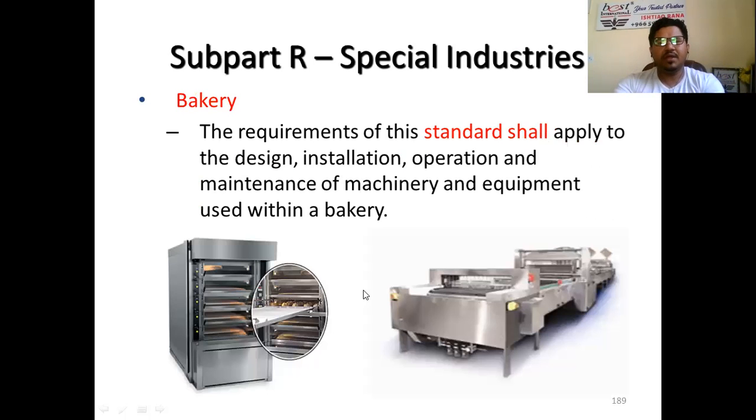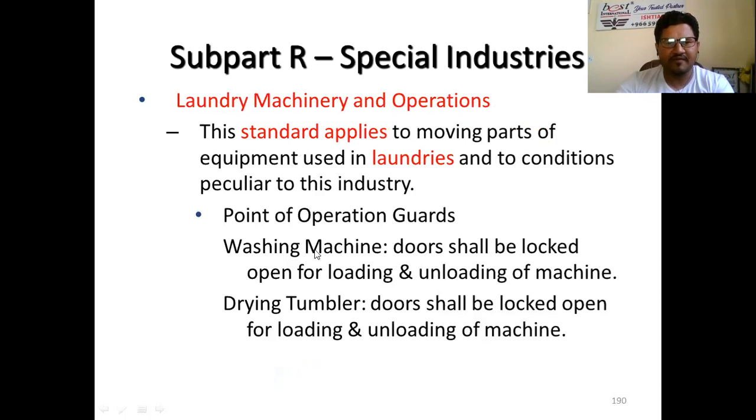Now, if you have a bakery, the requirements of this standard apply to the design, installation, operation, and maintenance of the machines and equipment used within a bakery. As I told you, as per the industry type, be more proactive, including laundry and operations. The same standard applies for laundries, and let me give you an example, like point of operation guards: washing machine doors shall be locked open for loading and unloading of the machines. The drying tumbler doors shall be locked open for loading and unloading of the machine.